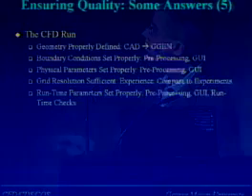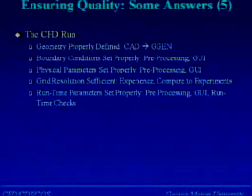I mentioned users because the user training is really the key to successful use of CFD, and user motivation, of course. I mentioned this graph before. If you look at the CFD, how do I ensure that the geometry is properly defined, that the boundary conditions are properly set, that I have the right physical parameters, that the grid resolution is sufficient? And really, the answer to this is GUIs. Right? So visual, visual, visual. Try to have as much visual input for the user as possible. Try to alert him to possible mistakes. That has, over the years, transpired as the best way of handling that issue.